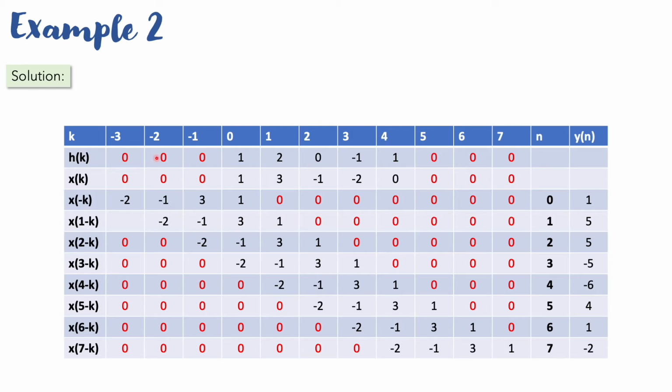In order to make them of equal length, like from -3 until 7, we fill our actual sequence with the positions of the samples, and the rest of them we fill with zeros only. So if we multiply them, we will get our answer as 0. That is why we do not multiply. We multiply only the places where the sample signal actually exists.